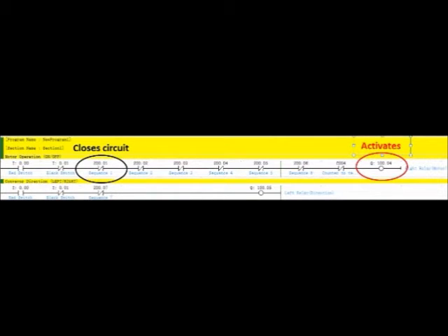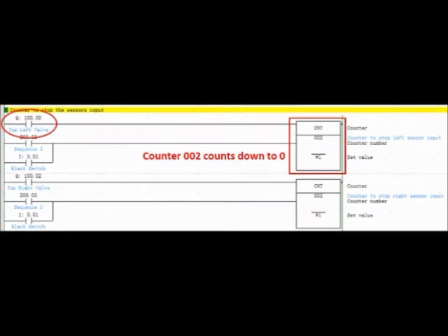At the same time the conveyor belt starts to move, the top left valve is also retracted back to its original position as sequence 1 is deactivated. To prevent 2 balls from dropping instead of 1, a counter is activated after the activation of the top left valve. What this counter does is that it makes sure that after the top left valve extends and retracts back to its original position, it will not do so again until the counter resets.